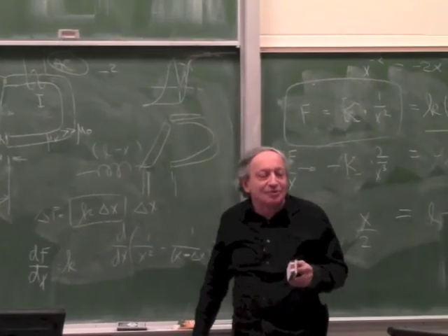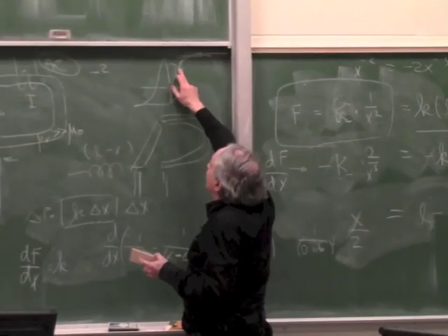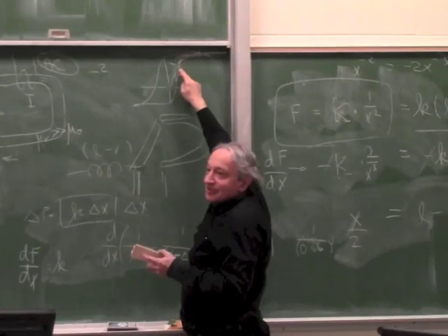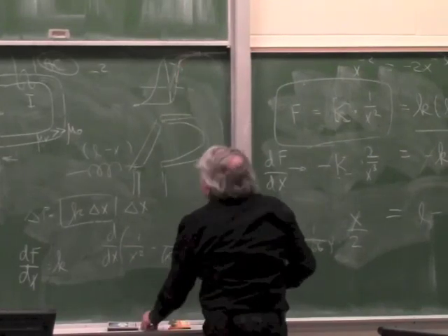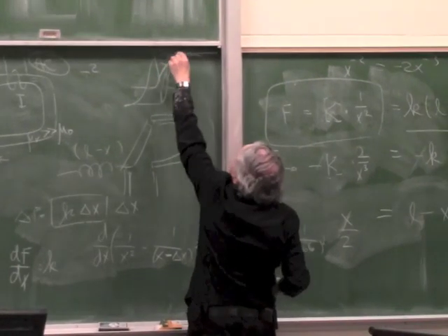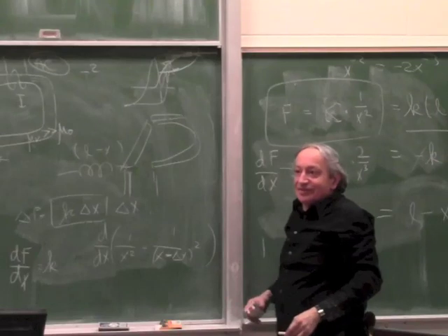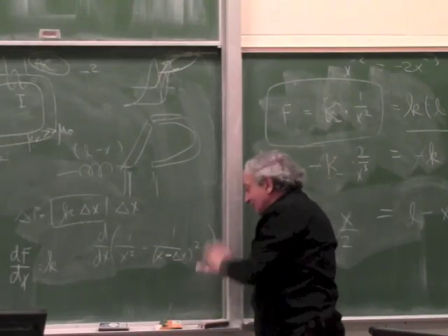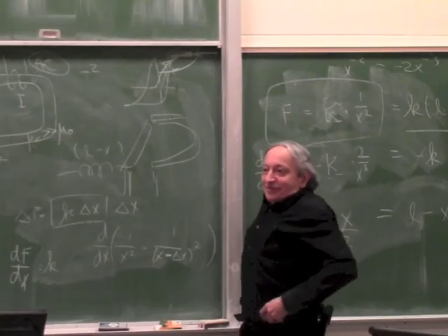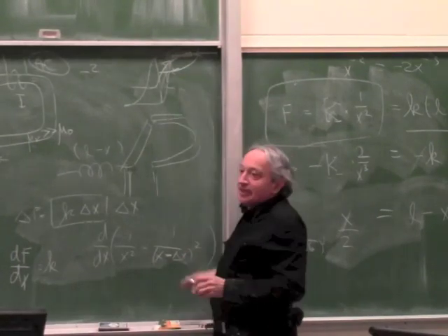It's not so simple to write a controller which, given where you are, knows the mu, because it depends how you got to this point. Right? The mu is different if you got to this point like this, or if you got to this point by coming back from here, the slope will be different. So it's actually not simple at all to say, no problem, I'll write some software which takes care of it, because it has many, many factors: temperature, which direction you arrived.